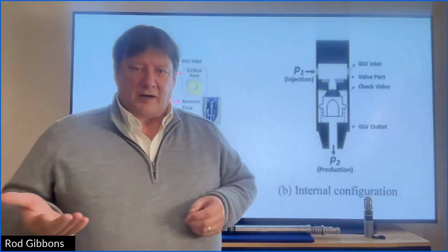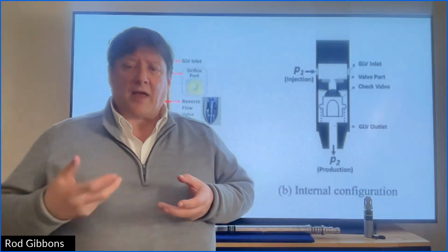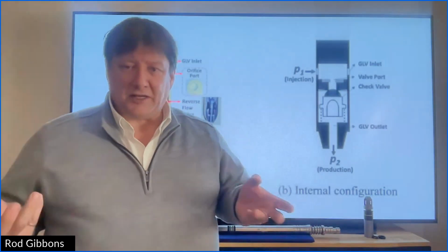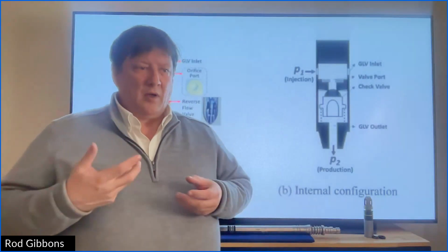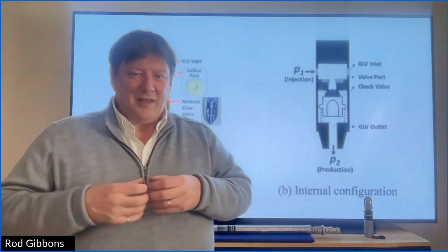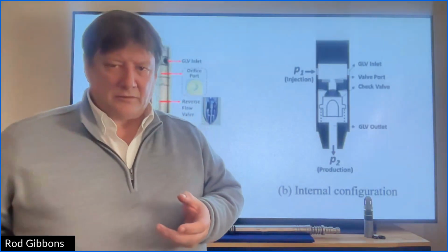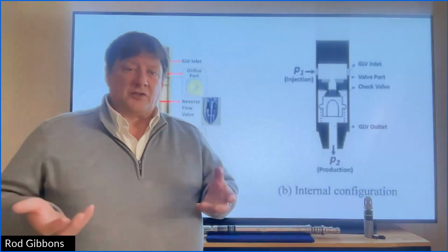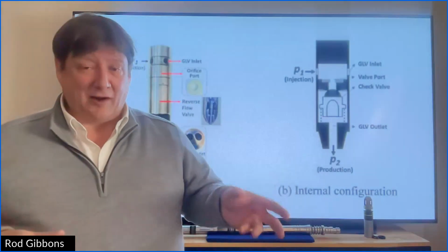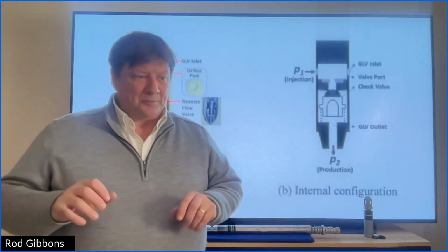gas compression is required. You're going to produce the oil, and we currently don't have a gas export line or a floating LNG facility, for example. So we can use the gas on the platform or on the facility, but we have to re-inject it back into the reservoir to conserve the gas. And I think no one would argue that re-injecting gas is a better idea than just flaring it. And there's clear limits for the amount of flaring you can do.